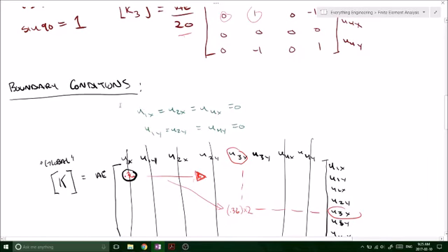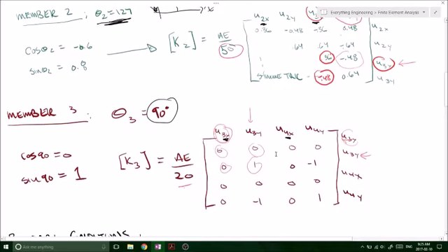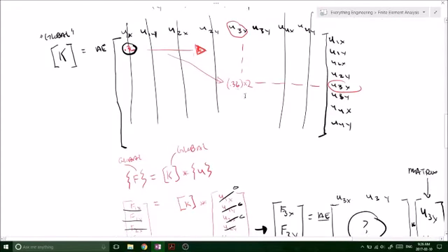Simple. And then we did our boundary conditions, right? So we found that the only nodal displacements were going to be at node number 3, because everything else had a hinge, or it was a pin support or a fixed support, so there can't be any movement. And then if we were to assemble the global stiffness matrix, we had to do a lot of running around, which I didn't really want to do because you don't really need to solve this problem. But remember that we have to find out each component, the matching components for every column and every row with our local stiffness matrix, and add them up. If we have anything overlapping, add them up, throw them in your global stiffness matrix.